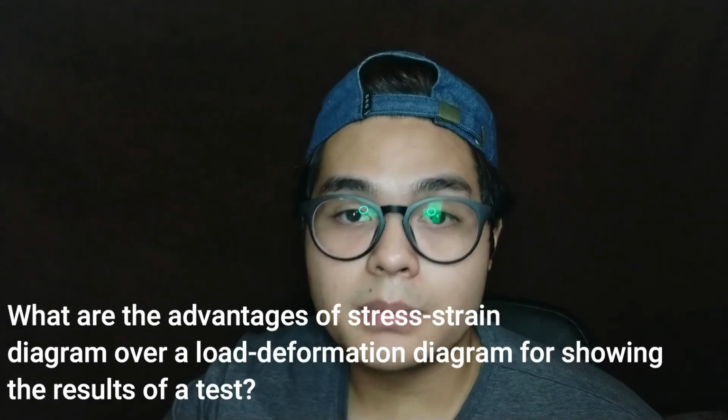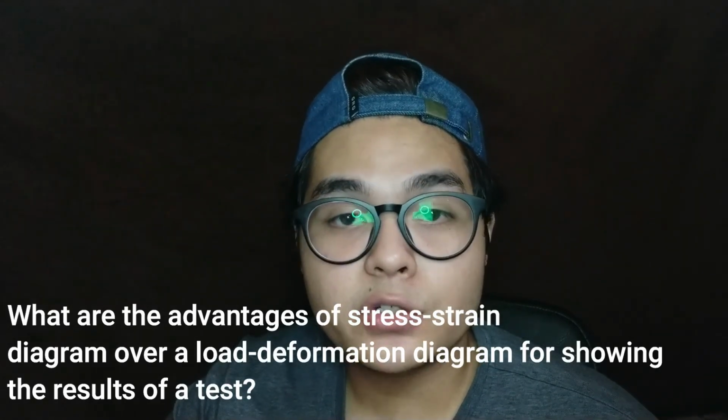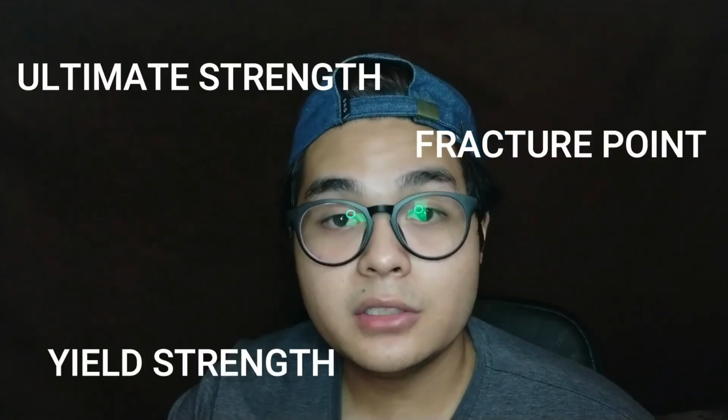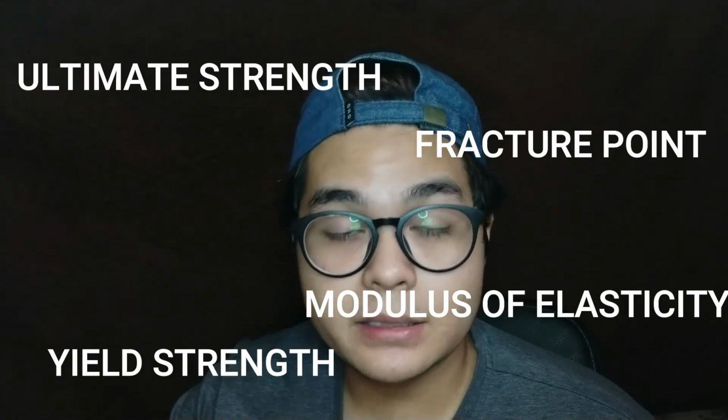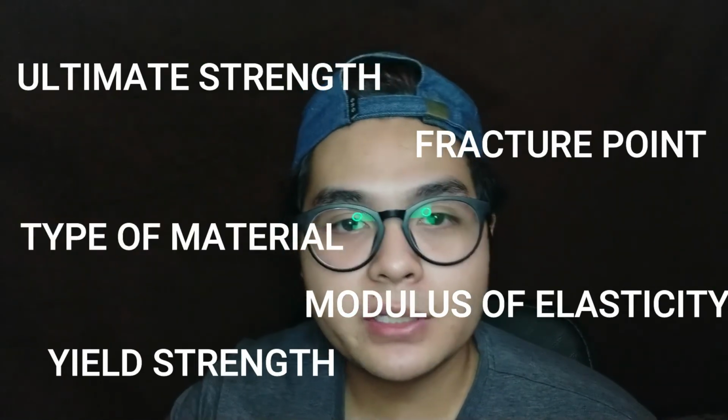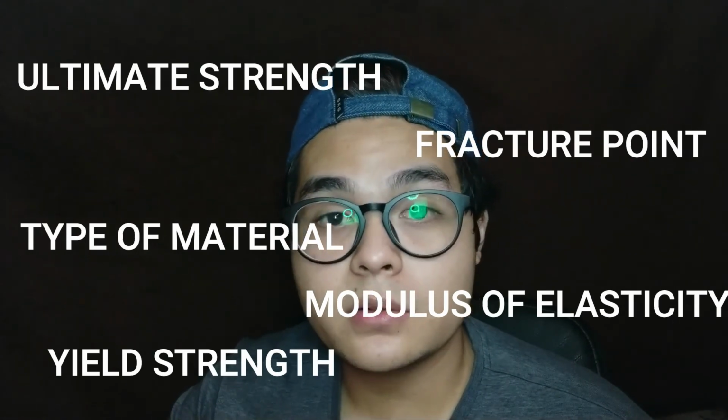Many properties can be obtained from the stress-strain diagram. For example, one could obtain ultimate strength, fracture point, yield strength, modulus of elasticity, which is the slope of the graph, and the type of material, whether it is brittle or ductile, which can also be found through the ductility ratio. Plus, calculations for safety can be made.